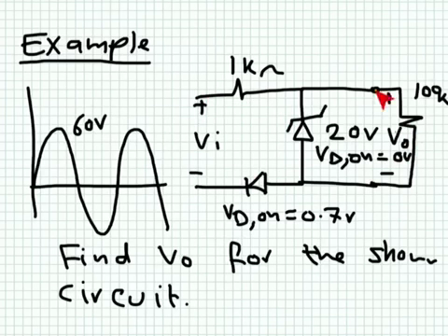So the voltage between here and here is simply equal to 0 volts. The output is not connected to the input. So this is when you have an input voltage between 0 and 0.7. Now, if the input increases above 0.7, but less than the voltage necessary to make this Zener break down, then this Zener diode is still off, but the external diode is on, and the circuit looks like the current is flowing in this branch. You can see it this way, and this one is completely off.